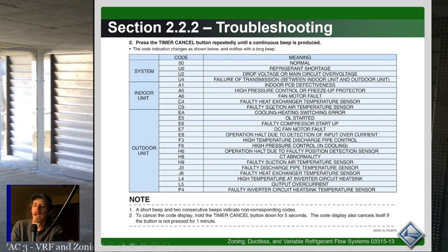Often the problems you're going to have are bad temperature sensors or faulty circuit boards or refrigerant leaks on flare joints, things of that nature. You're going to have very few other more major problems, although you can have bad inverter compressors or bad inverter boards or whatever. But most often, your errors are going to be based on sensors and things of that nature, or poor installation. Poor installation is exacerbated on something like a VRF or a mini split.